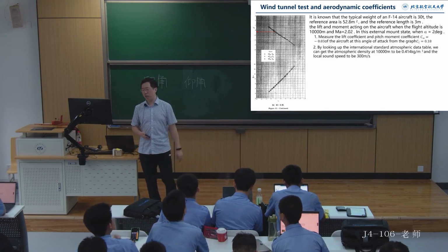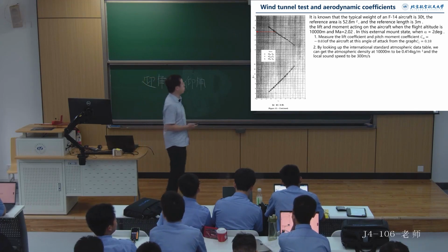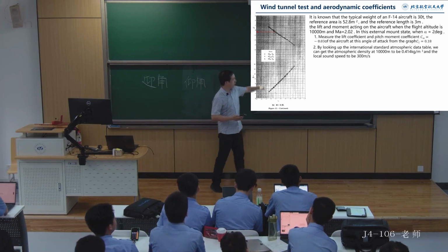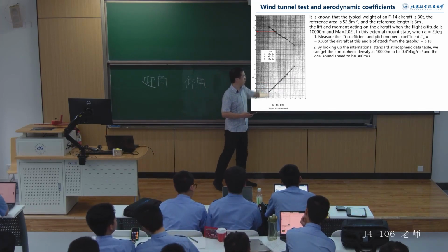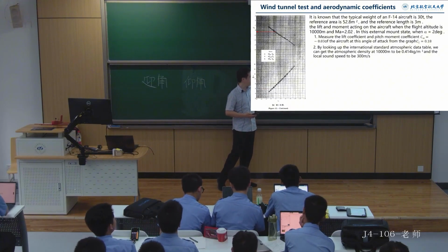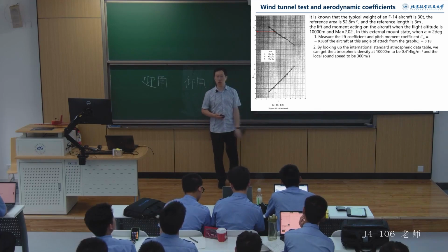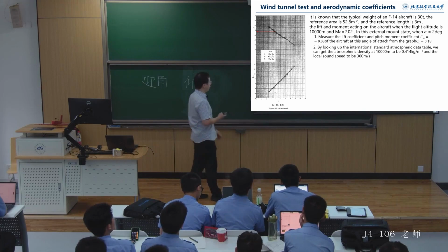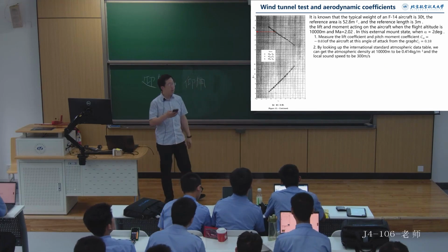Here, because the aircraft is in a symmetrical state, the side slip angle is 0, so we only care about the angle of attack. Therefore, we start from a 2-degree angle of attack, then draw a line from the side to intersect with our experimental curve. Then we look down the chart to find the corresponding lift coefficient at this moment, which should be approximately 0.18.